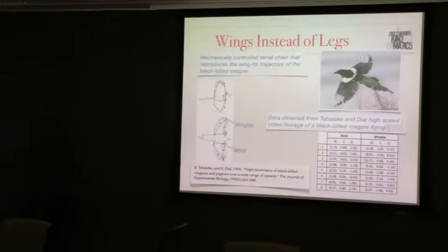Every one of our designs, for example, when we do the 6-bar linkage, we'll get maybe say 20,000 solutions. We have to analyze every one. And what we want to make sure is there is a range of motion that includes the task position. It will be reversible in that range of motion.